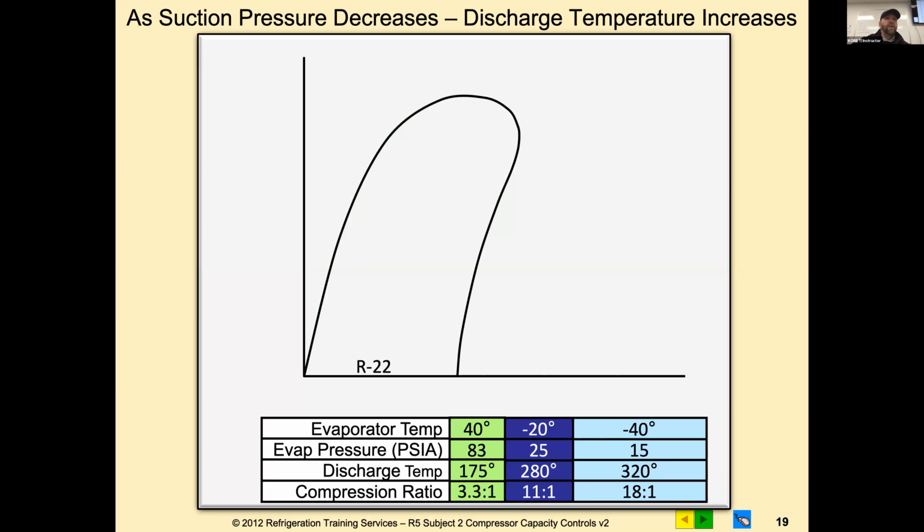So has everybody seen an enthalpy chart? Everybody know how to read an enthalpy chart? Okay, so this is an enthalpy chart. What that tells us is our refrigeration effect. You've got your enthalpy, which runs across in BTUs per pound for the type of refrigerant, so your saturated liquid to your saturated vapor. We'll go over the lines real quick.